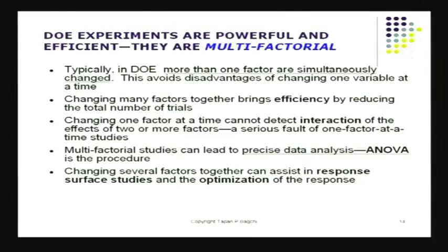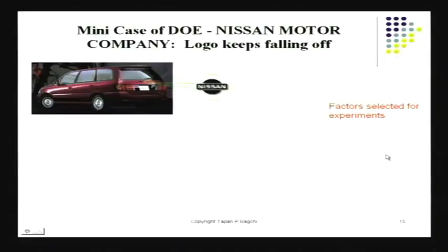So in fact, what we've figured out so far is we've got multifactorial situations that we must manipulate, and typically we'll be manipulating more than one variable. That's what we'll be doing. We may change more than one factor. We may have their distinct settings there. For data analysis, we'll be using ANOVA. That is something that we'll be doing. Our ultimate goal is going to be to try to construct some sort of a response surface so that we can come back and find the optimum settings for the experiment. Without doing that, we of course cannot really say that we have really helped the process.